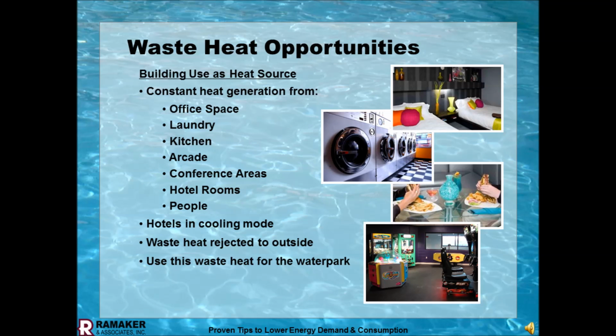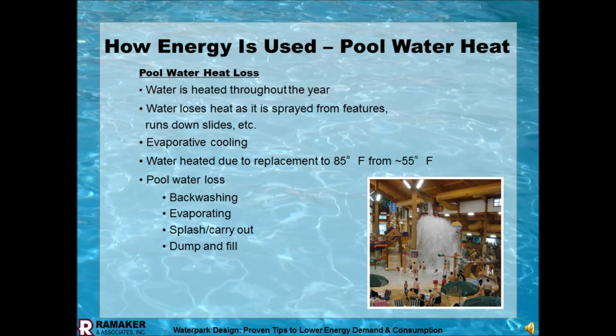So the heat opportunities, like I mentioned, are the arcade, the kitchens, laundry, hotel rooms. The hotels are in the cooling mode, and you reject the heat to the outside. How can we use it in the water park? So pool water, people like warm water, 85 degrees, 84 degree pool water, hot tubs, 100, 104 degrees. The water's heated throughout the year, so it's a constant cost that you have.